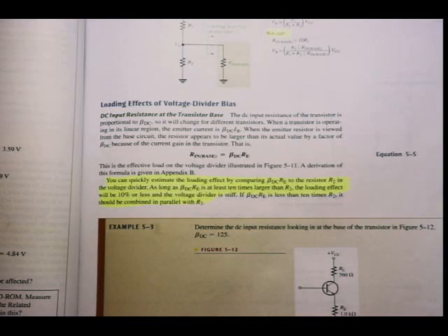So what am I doing here? If I go to this circuit here, there's my voltage divider with load. Doesn't it look similar to the circuit I've just discussed with you? I can see this R in at the base as my voltmeter, isn't it? As the resistance that is in parallel with R2. Okay? So it's the same thing that happens. Current that's going to split in that direction and in that direction.